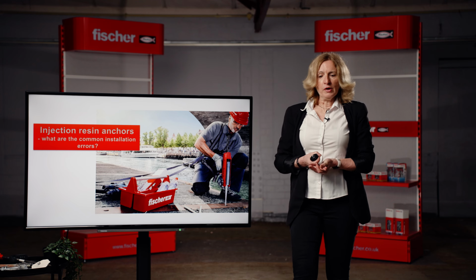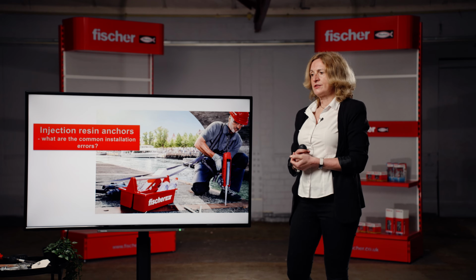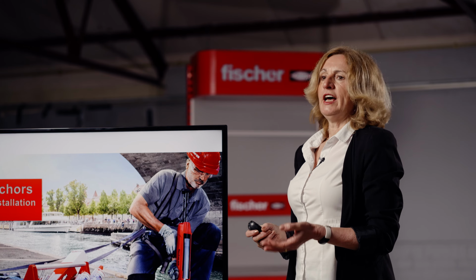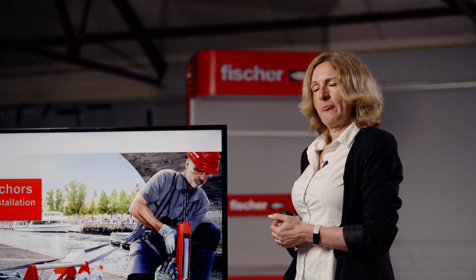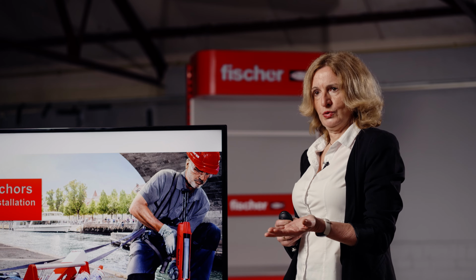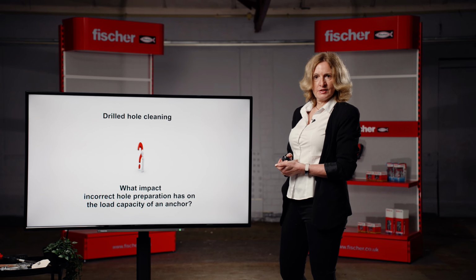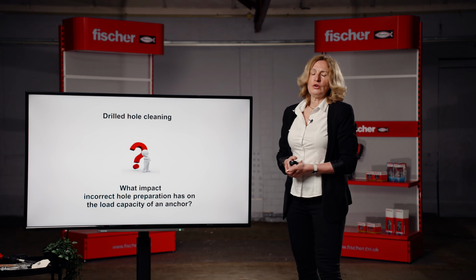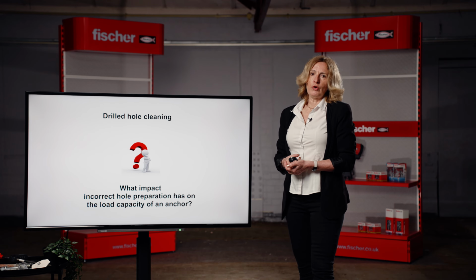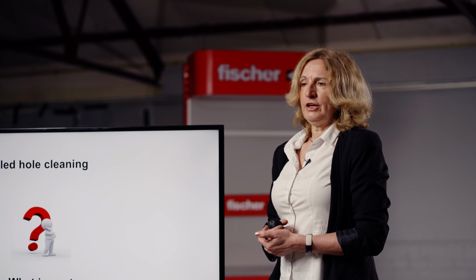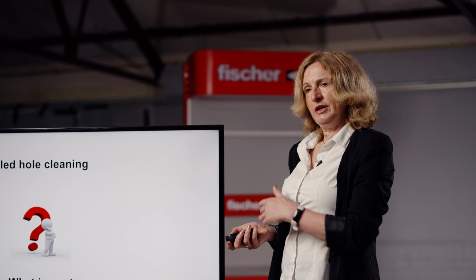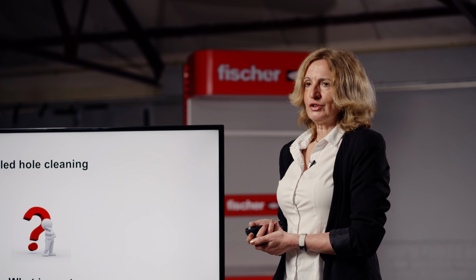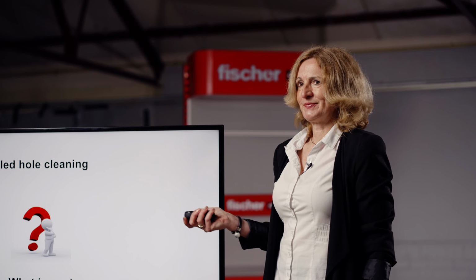So let's have a look now at installation of injection resin anchors. What is a very important and very common issue on installation of injection resin anchors? What is usually not used? Hole cleaning accessories. Okay? If you don't clean a hole correctly before you inject the resin into the drill hole, what will happen? It will reduce the design resistance of the anchor. I will show you in a video the impact of not cleaning the drill hole correctly.